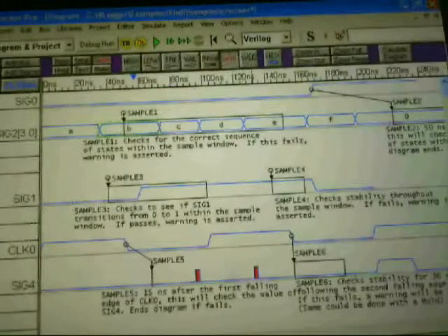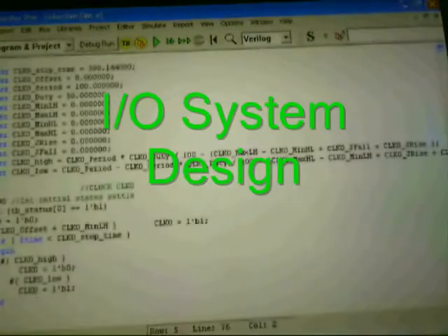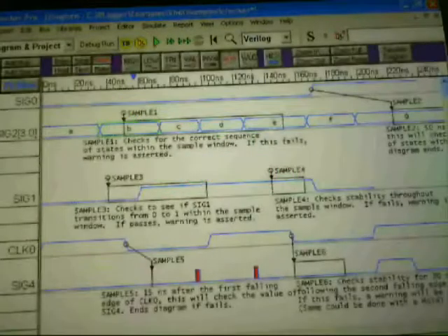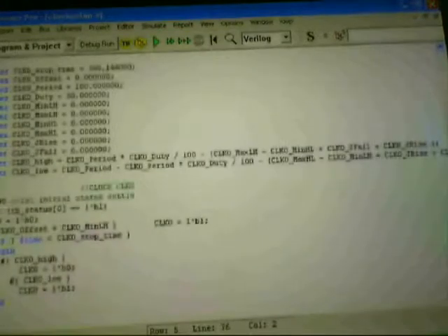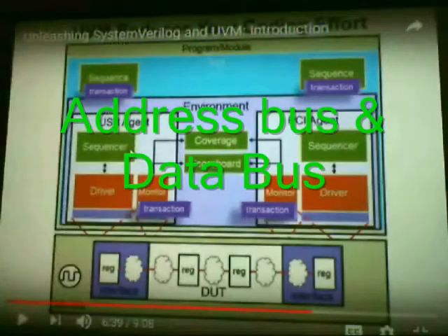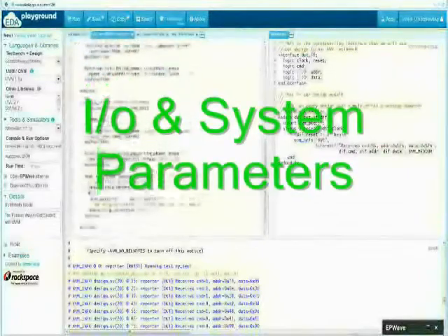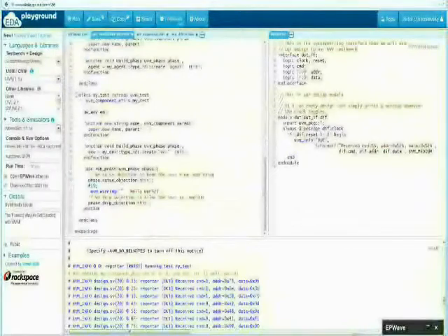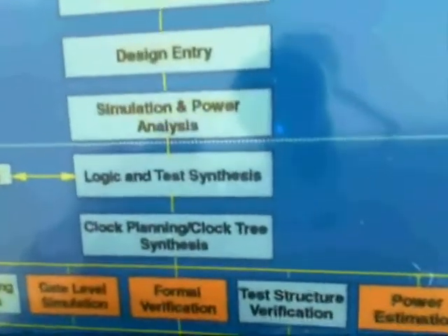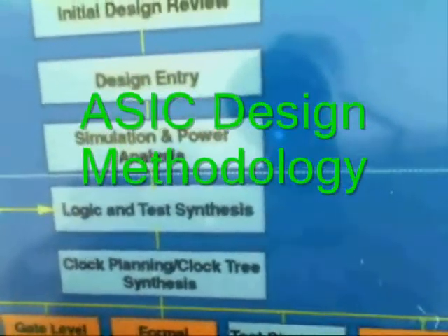Follow the design of an I/O system. 1. List the different types of I/O devices to be connected to the machine, and list the standard buses that the CPU will support. 2. List the physical requirements for each I/O device. This includes volume, power, connectors, bus slots, and expansion. 3. List the cost of each I/O device, including the portion of cost of any controller needed for the CPU.